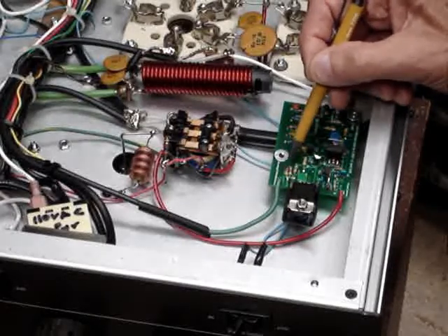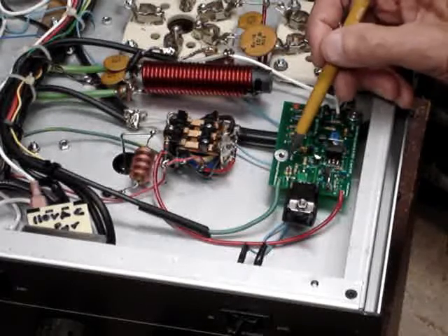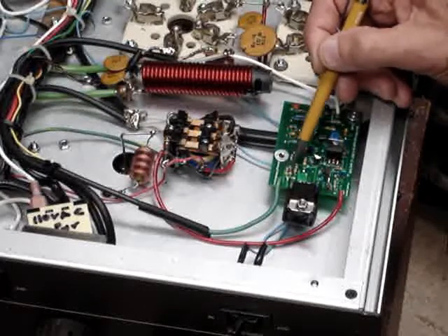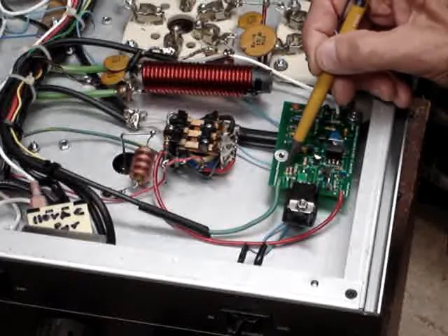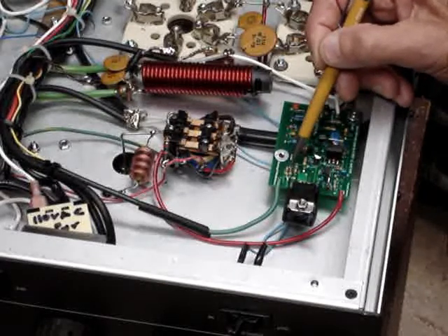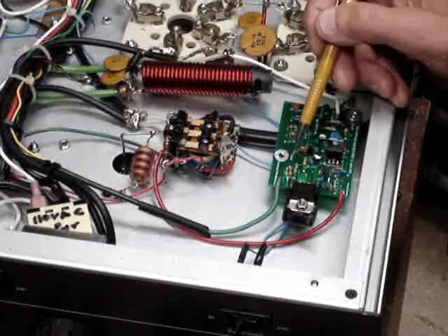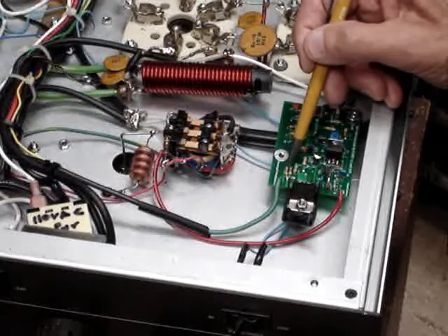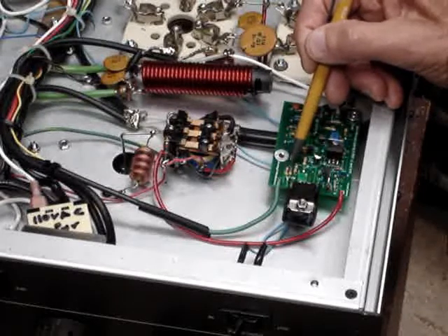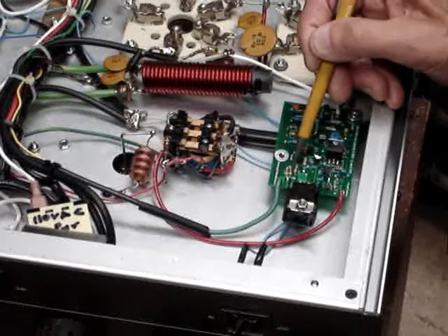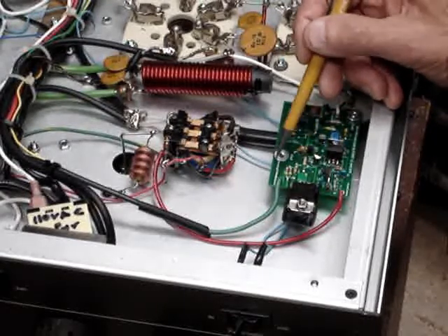typically around 2 to 3 K seems to work good. And if you do the calculation, you don't really need a lot of high power resistor. I made this, I believe, a 1/2 watt. The voltage, when it's not turned on, only goes up to 16 volts with this resistor combination. So if you calculate 16 volts squared over 2.35 K, you'll see what the dissipation is of this. It's not as great as one might think, but you know, a 1/2 watt resistor if you want to be conservative.